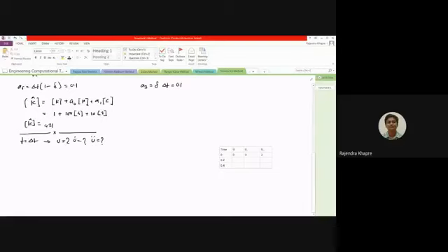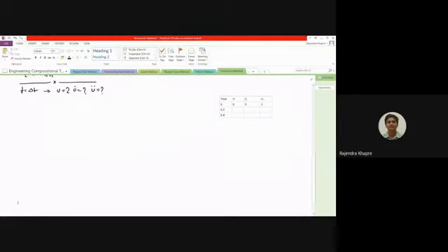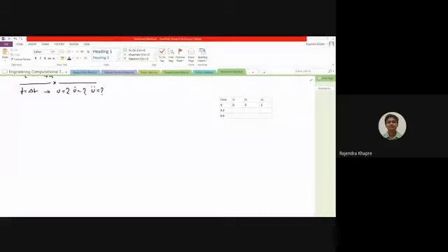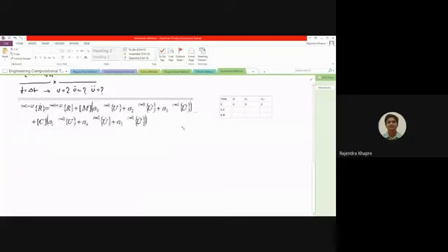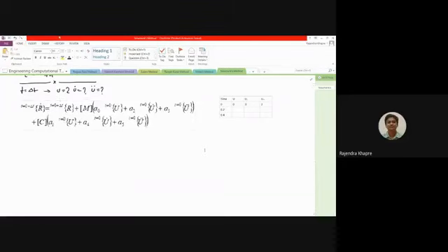So this is my aim. For this purpose we have to follow the stepwise process. In this process, the first thing we have to do is calculate the effective load vector at that particular time interval. Here I'm just copying and pasting the equation from the notes, so that the effort can be reduced. The effective load vector depends on the load value at delta t, that is the r value at delta t.